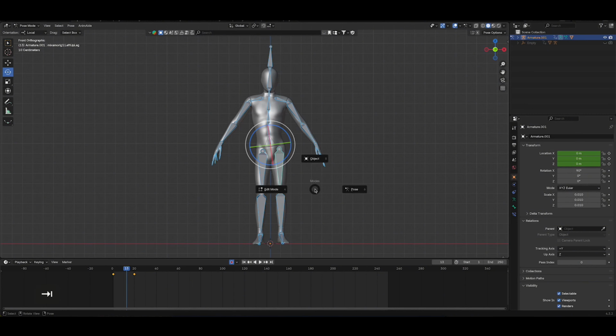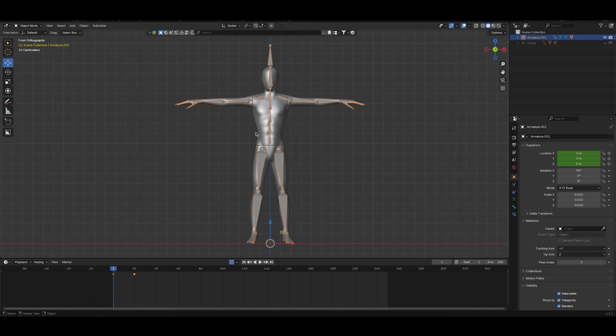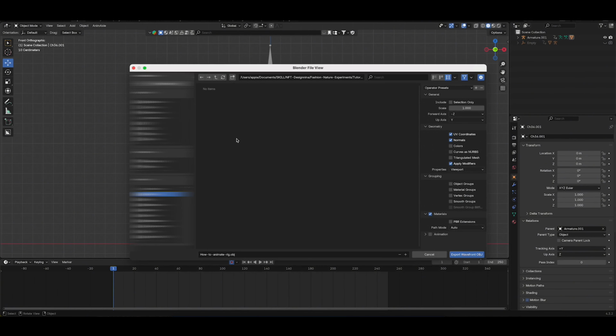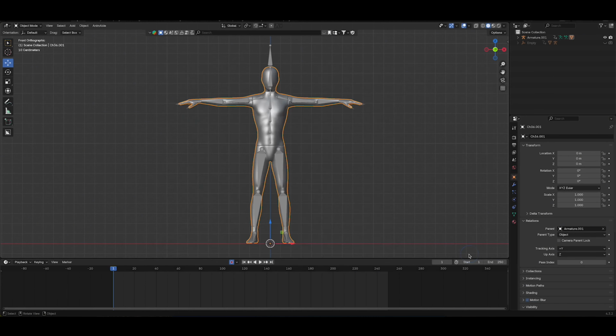Now let's save all of the files for Claw 3D. So let's go to the very first frame. I'm going to save the T-pose first. Let's select only the mesh. We don't need the armature for the object. Let's go to File, then Export, and find Wavefront object. Press it, then save it somewhere where you need to save that. Make sure that you check the box selection only. That's quite important at this stage. Then export. Just wait a moment. I'm going to add the T to the name of the object, so I can differentiate them.